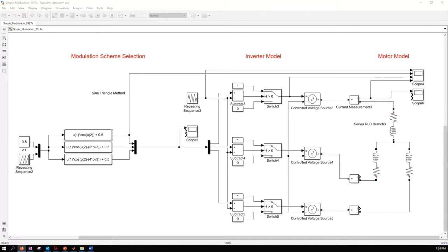If I want positive voltage for a phase, it will modulate above 50%. If I want negative voltage, the PWM will go below 50%. And now with respect to another phase, you will see either a positive or a negative voltage, which gives me my sinusoidal outputs for the machine.